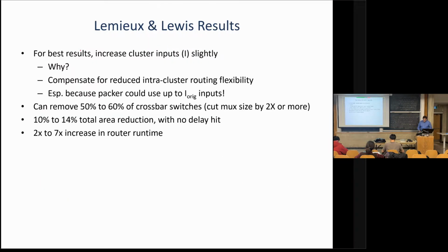So that's another principle: for all these little sub-problems, if you can leave a little bit of slack, so the router still has a bit of breathing room, it makes the overall routing problem a lot easier. So in the clustering problem in FPGA CAD tools, if you could bring in a maximum of 30 inputs, you usually don't tell your clusterer that. Or you tell it, only do that if you absolutely have to. Otherwise, don't go above 26. Because with 26, you've got some wiggle room. It's much harder to get blocked.